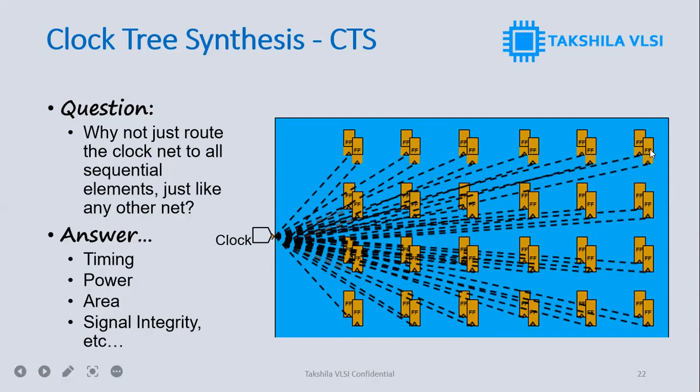And suppose if there is a long net, we'll place some buffers also, clock buffers, in this particular net. Suppose there is one block which is sitting very far from the source. Without placing the buffers, if you give the clock tree structure, then there will be signal loss due to the voltage drop.